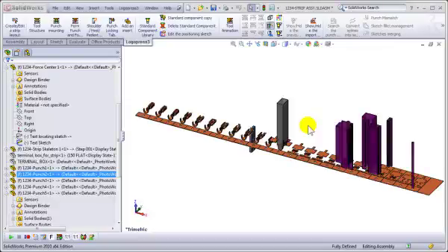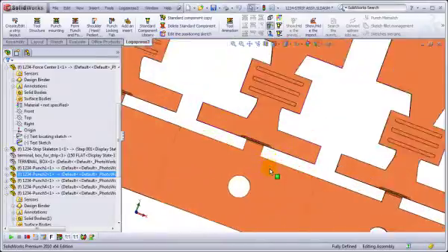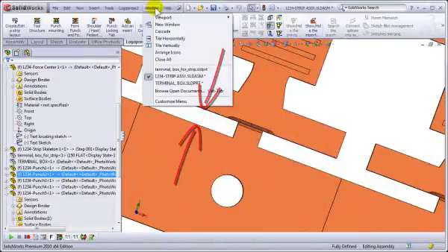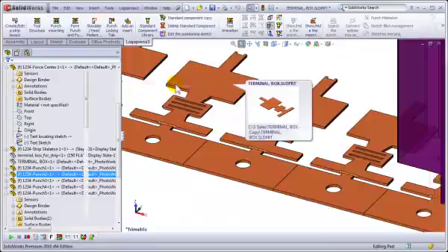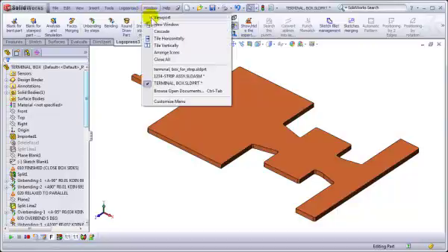We just finished creating a 59-minute strip layout for this complex box terminal, and let's say it was for estimating purposes, so we cheated a little bit. But what will happen, let me zoom in on this area. For example, once we get the order for the tool, we need to update this strip. For example, in this area, that won't be parallel. There'll be an angle there, and that's how all terminals like this end up being.